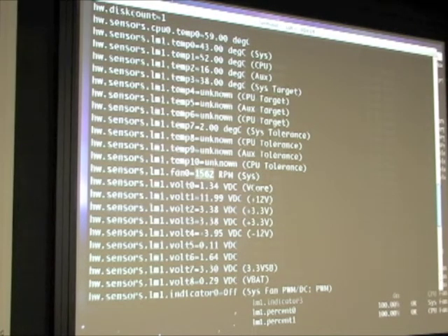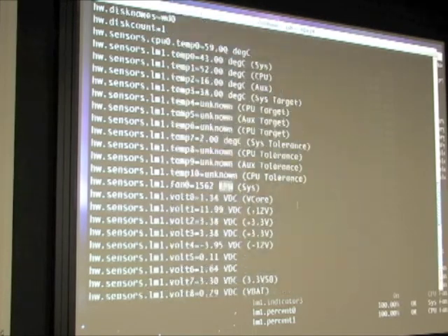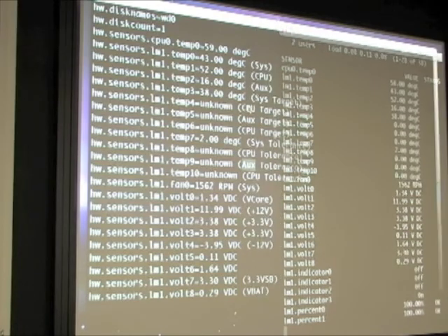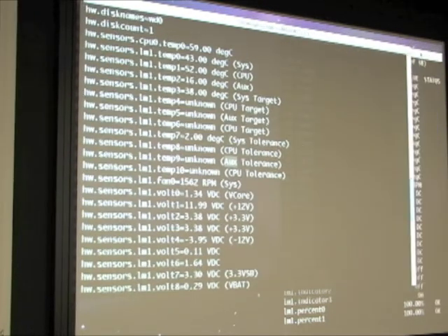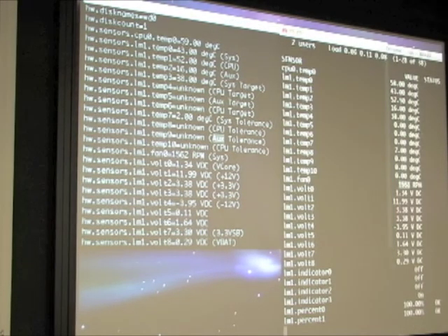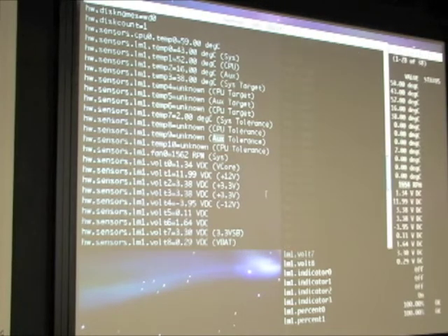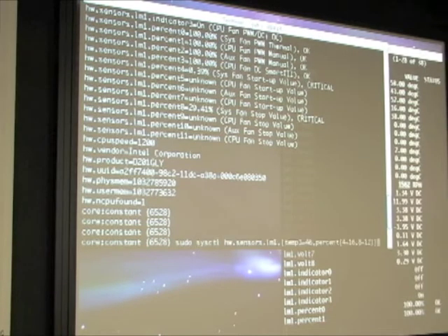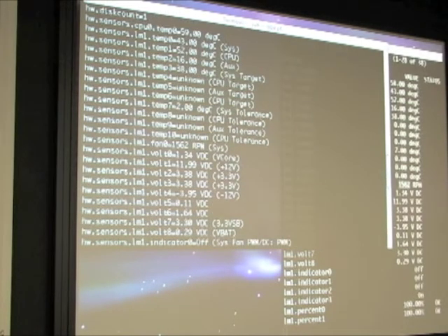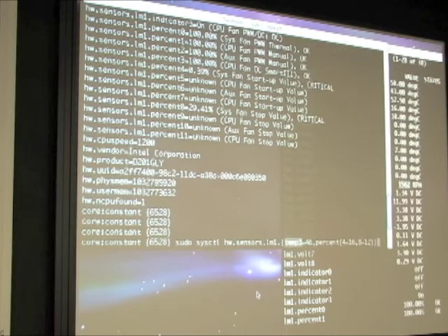So currently you can see that the fan runs at 1500 RPM, rotations per minute. So let's try to change some settings so that it will run at lower speed. So you can see here in the active refresh, you can see the current speed of the fan. So in this example, I can set the thermal cruise mode of that sensor, of that system target temperature, from 38 to 46 degrees. And I can set the %4 sensor to 16 and %8 sensor to 12. So let's see what's going to happen.